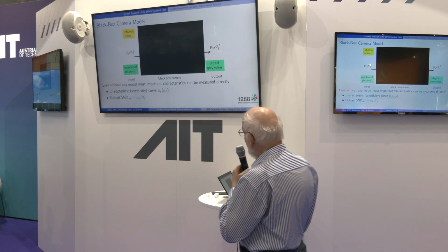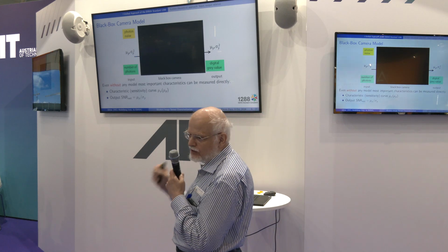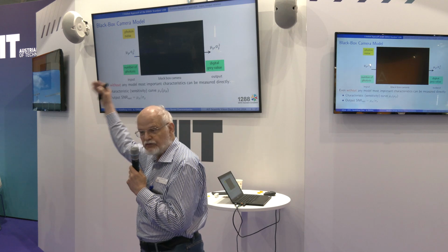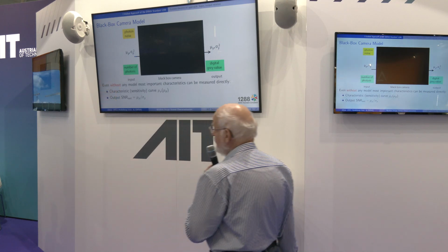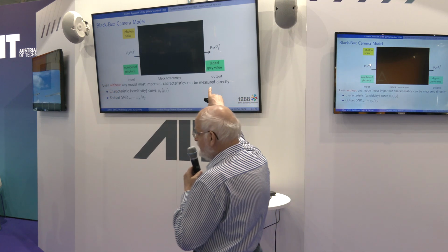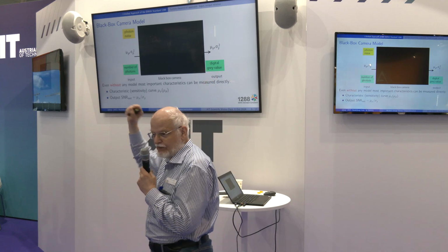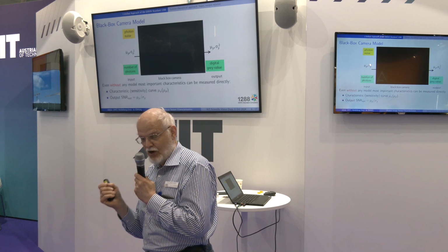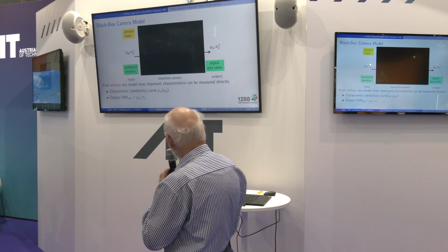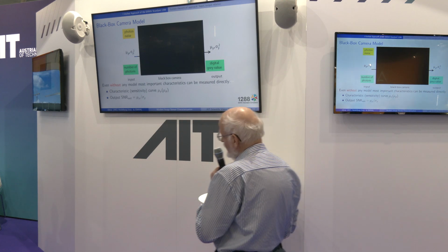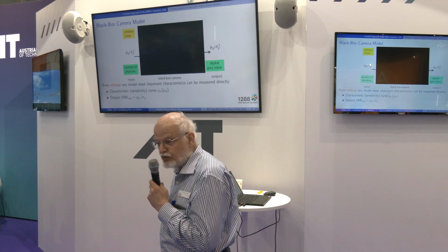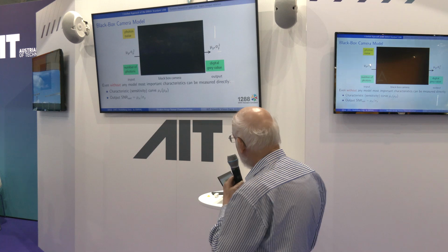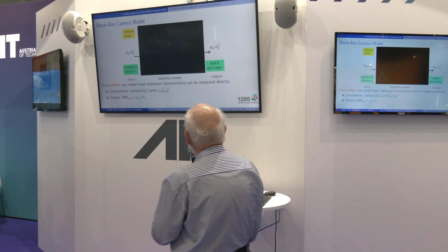That means what is the signal I get as a function of the number of photons, basically from complete dark to saturation. The second thing you can measure, since you measure both your mean signal and the variance, is the quality of your output signal. You know how good is actually my signal. And that is what we call the output signal to noise ratio. It's the mean value divided by the standard deviation.